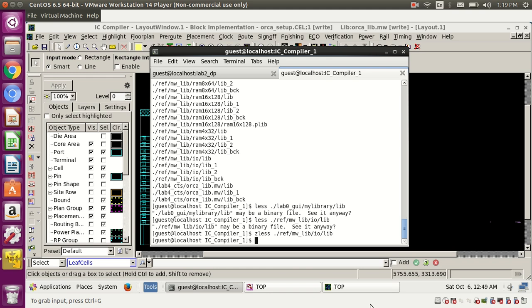But what is the clock you have given to the flop? What is the clock period you have given? Just see the waveform, what you have given. The output came at 10 and it went to 0 at 12.5. That means from 0 to 12.5, the duty cycle you are giving is 2.5. So in that 2.5, the hold check and setup check need to be done. So is it the clock? Is it our actual clock?